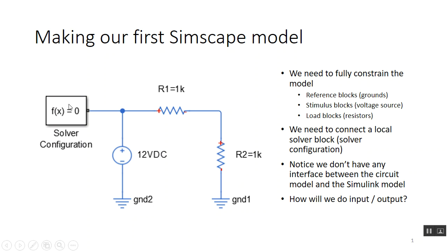But the reason is because having a local solver gives you the capability to say, this electrical network needs to solve maybe with a time constant of something like 10,000 or 1 millionth of a second, where you would be wasting a whole bunch of time if you had to solve mechanical networks that fast, because their time constants aren't nearly so small. So that's one of the side benefits.